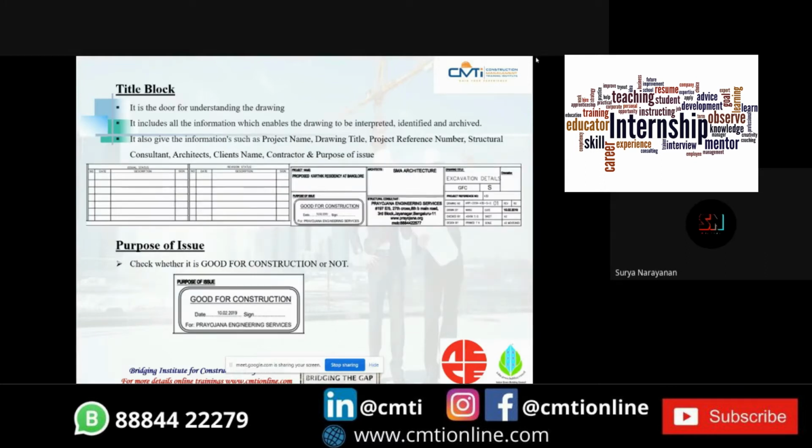So title block. The very first thing which you have to note when the plan is given to you is the title block, where it gives information such as project name, the drawing titles, project reference number, structural consultant, architects, client's name, etc. And this is how a title block looks like. And the purpose of issue is very important while reading a title block. We should check whether it is good for construction or not.